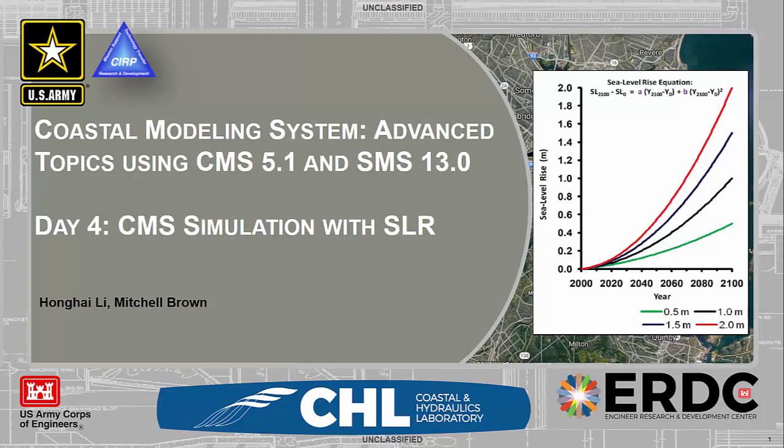What I'm going to talk about today is that we now incorporate the sea level rise curve into CMS simulation. Like you see in this cover page, there's a sea level rise projection from 0.5 meter to 2 meter. Based on the sea level rise equation at the top, we can have a rising curve, and we can now read this curve into CMS and make a long-term simulation.